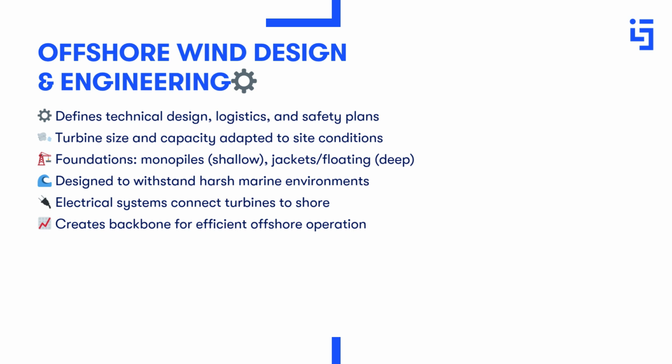This leads to foundation design. Structures must support large turbines under constant exposure to waves and wind. Monopiles are common in shallow waters, while deeper sites require jacket structures or floating platforms, with seabed conditions guiding these choices. Electrical infrastructure is then developed to transmit power efficiently.